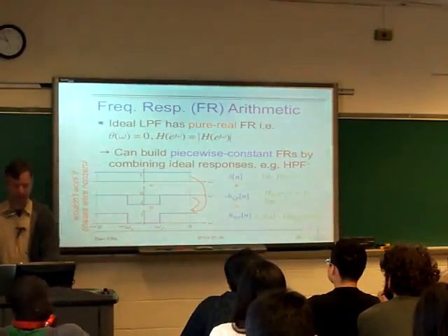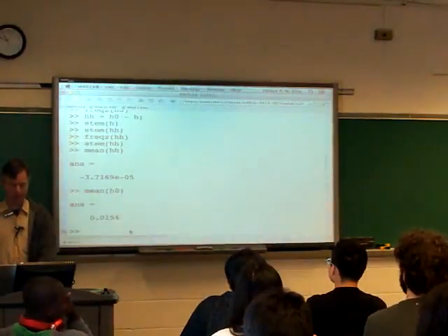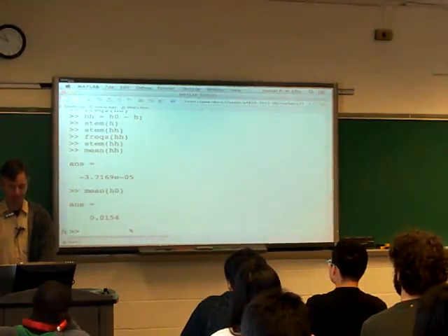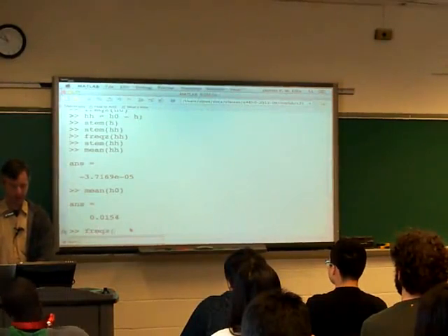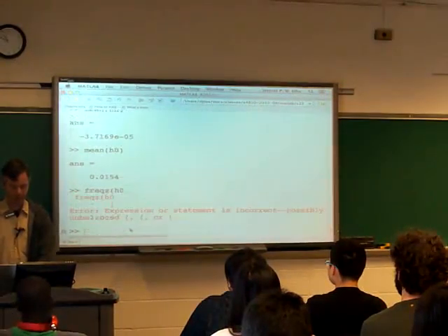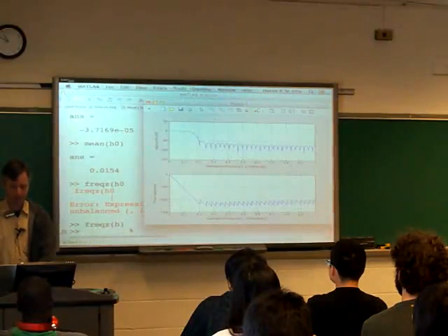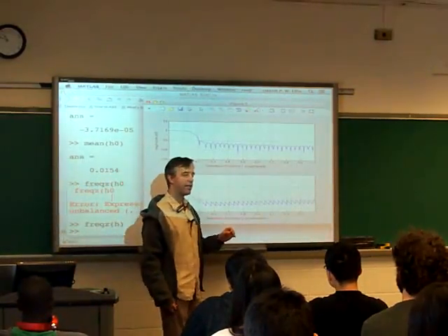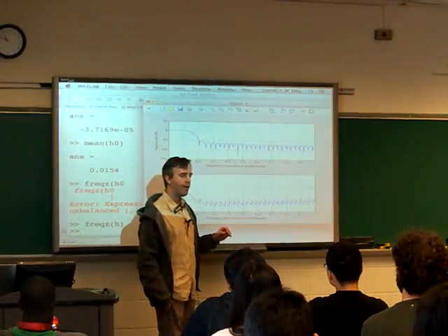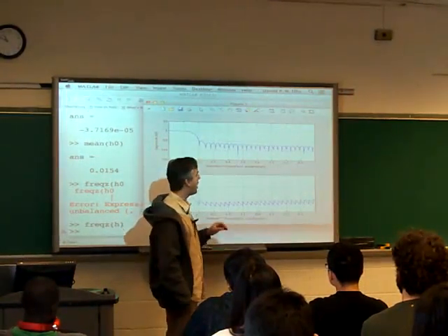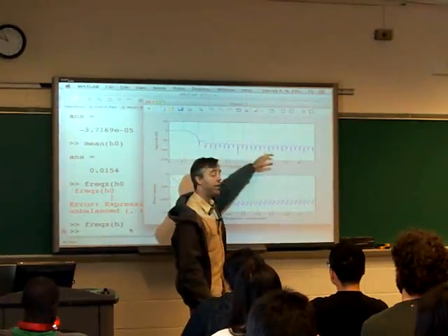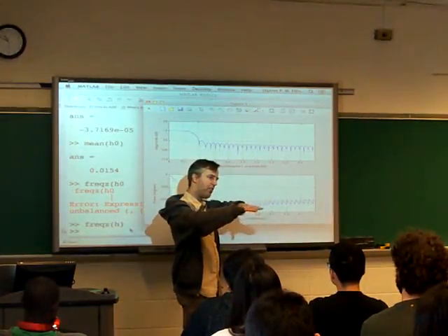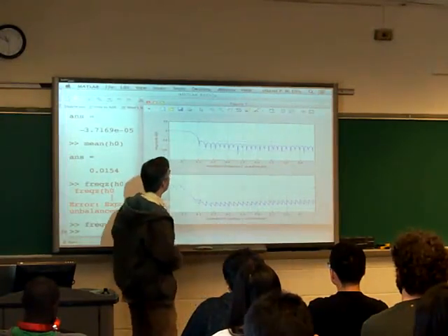We got this filter, that actually didn't look that bad. Let's look at the original one, frequency of h. Oops. Remember that when we were trying to get our best possible filters in the continuous time domain, we like this idea that the ripples should all be the same height, because basically, if they're all the same height, then we've kind of balanced the distortion, and so we're in good shape.